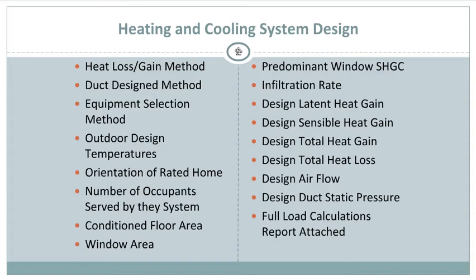Again, you need to remember the number of bedrooms or the number of occupants. The way they match occupants is that there should be 1 occupant per bedroom, plus 1. So if you've got a 4-bedroom house, you're going to have 5 people that occupy that house, more or less. So that's how they match it up. And then again, for a HERS rater, anything that is 70 square feet or larger and can be used as a sleeping area, such as a den or a library, can be counted as a bedroom. Okay?